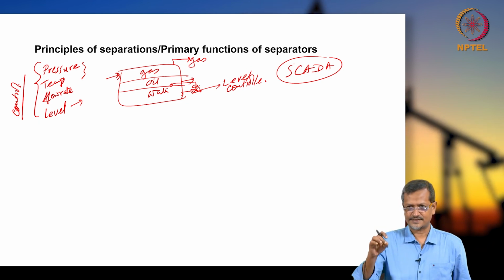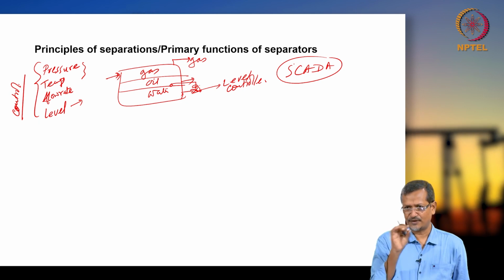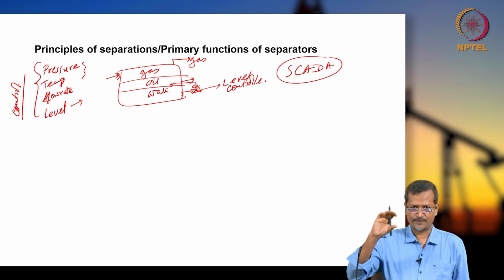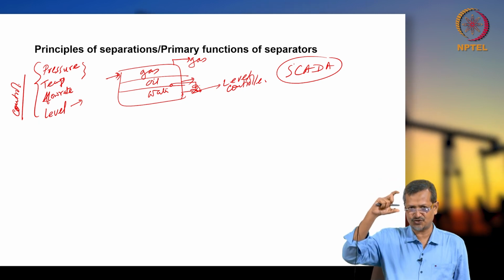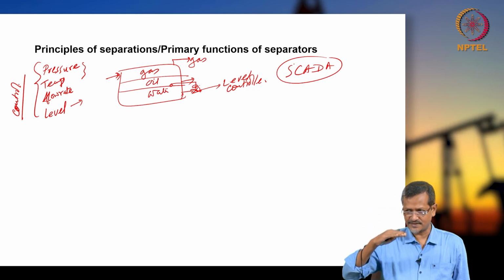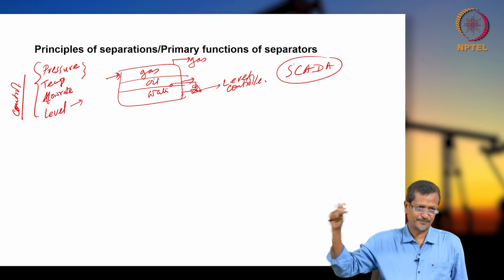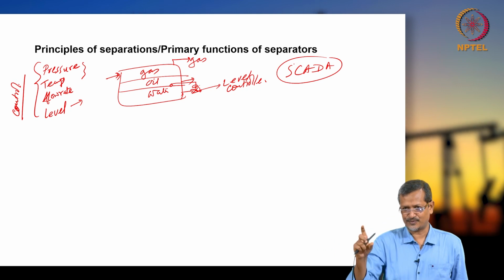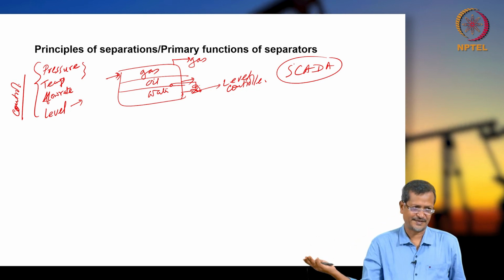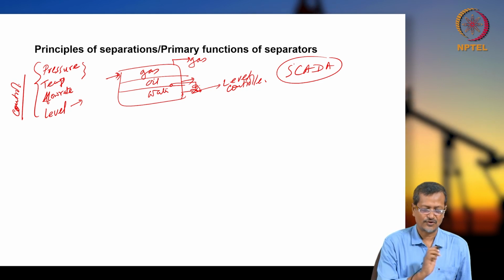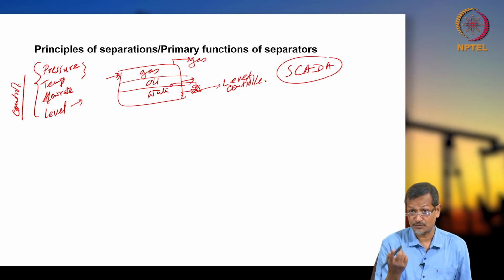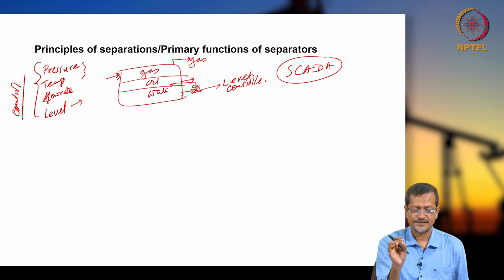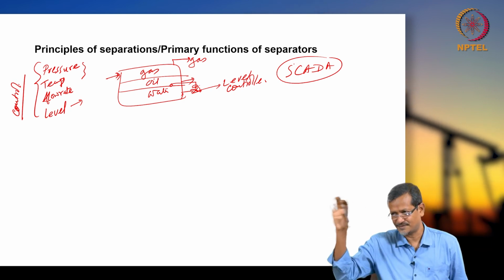Okay, so you have an electronic system. This electronic system will give signals to your control office, and you can check which parameter is changing and which is not desirable. So there will be a lower limit and an upper limit. Your level may be in the range of 2 centimeter to 5 centimeter. So if the level changes from 2 to 1 centimeter, or 5 to 10 centimeter, that means there is some fault, and you have to check that fault area. If you do not control that, there will be something much more disastrous or problematic in future. Okay, so level control is important, and for pressure, one is pressure control, one is pressure monitor. So you have to monitor, then you have to control. All the things will be given to your data acquisition system, that master computer system.